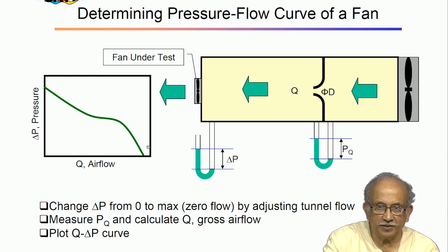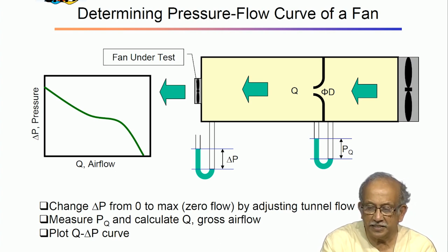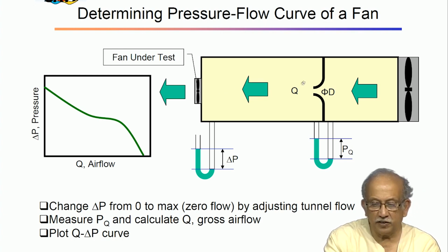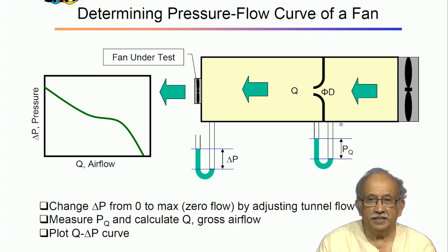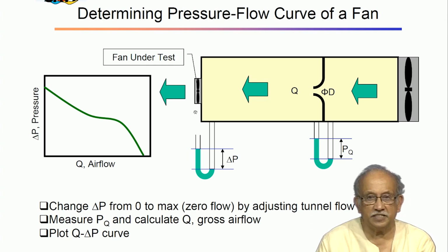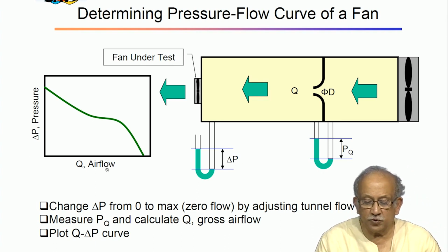I will talk to you a little more about it. Another way of making it is, imagine you create a baffling section and you have an airflow sensor and a pressure sensor, and then you baffle it, increase and decrease. So, we know the airflow, we also know the pressure across that, and then you know the pressure from inside this chamber to the outside chamber. So, the change in pressure versus the Q can easily be plotted out.